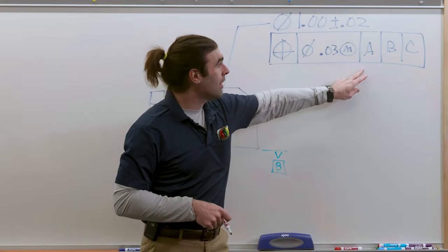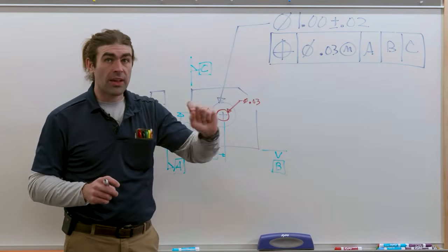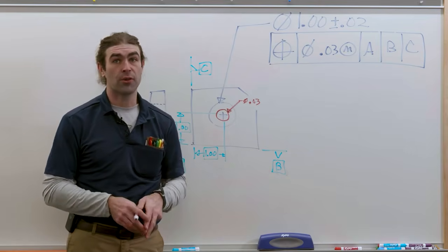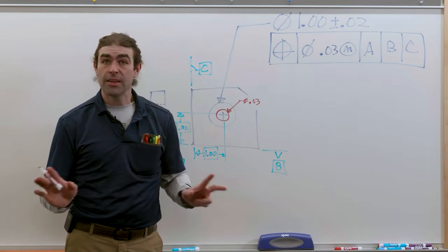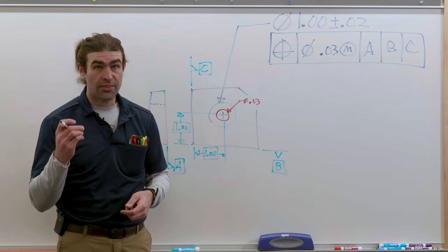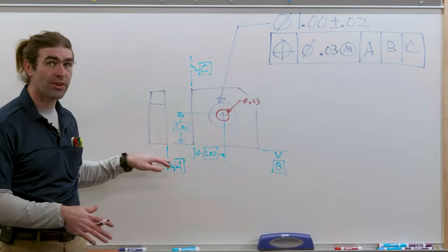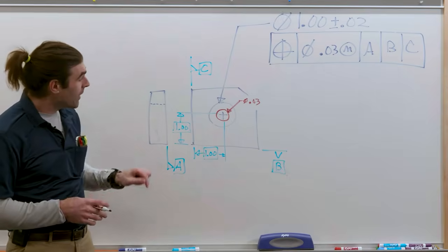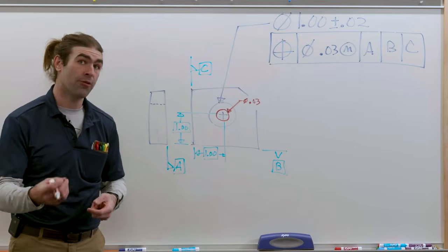Next, now this is important, are datum references. Most of the time, they will be written A, B, C because it's a popular choice for designers. It makes it easy to read drawings because people are used to seeing it. It does not have to be A, B, C. It's in the order that the part is set up for inspection. So datum A should be a mating surface, the largest and most important mating surface. Normally, for a block like this, it would be one of the largest planes, right? That gives you good repeatability for inspection.